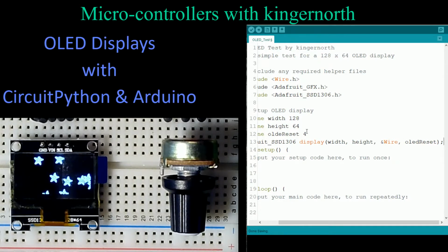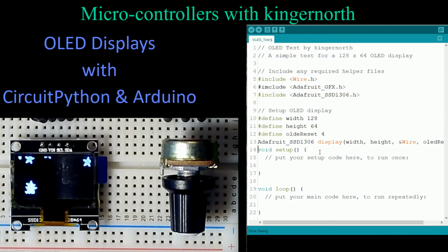If you really wanted to, you could hard code those numbers right into this line and you don't have to create variables for them. The advantage of doing this is that now I could have multiple boards and I could just do the same thing over and over, and create multiple displays. I can create them with slightly different addresses. There is another address parameter you can put here on the end if you need it. If you need the 5th parameter, you can do the address. So that's where that lies right now.